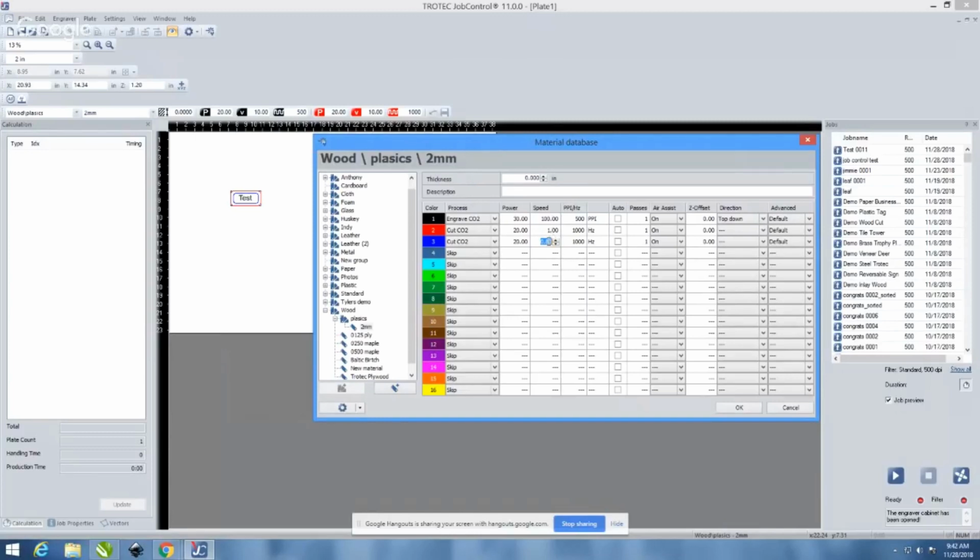On our machine here, 100 watt, we might be at 0.7 or 0.8% speed to get through a 1/4 inch piece of acrylic. It really depends on the thickness, but for it to be fractional is completely normal as far as that percentage is concerned for cut speeds. Yeah, and you can go 0.75, 0.76, so you can adjust the percentage to that degree, and that usually helps with different cutting materials.